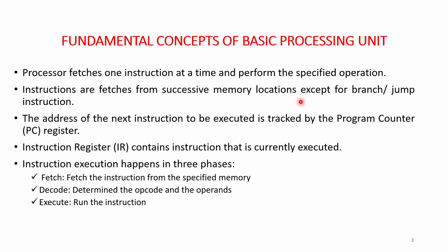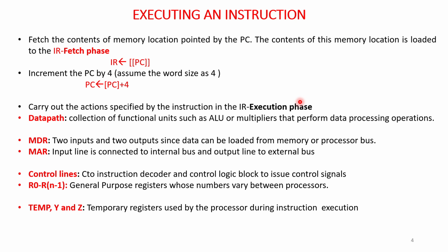To execute any instruction, we have to go through the following steps: fetch, decode and execute. Fetch includes fetching the instruction from the specified memory location. Decode determines the opcode and operands, and execution is nothing but running the instruction. Executing an instruction involves the instruction fetch phase.